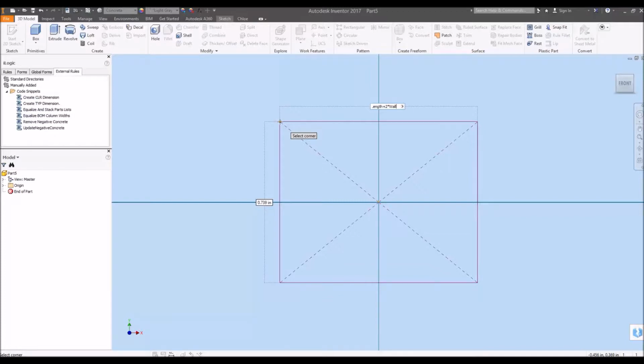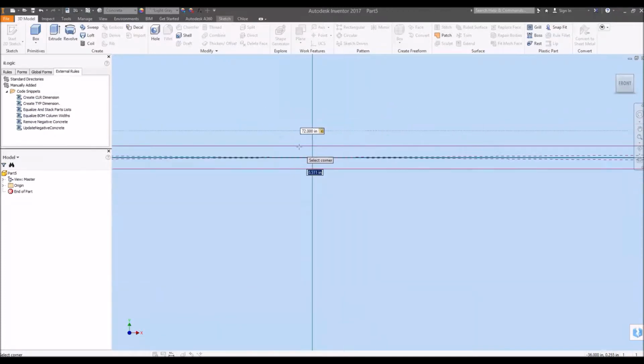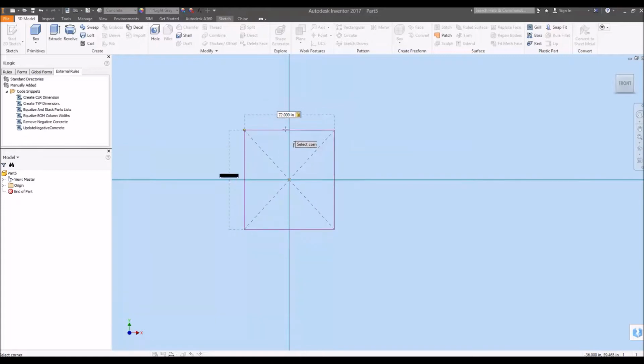Go ahead and hit the tab button to reduce the time spent clicking, and it should automatically put you into edit mode for that vertical dimension on the left there. If you see it highlighted in blue, we're going to basically do the same thing. We're going to type in width plus 2 times our wall, it changes from red to black, and let's go ahead and hit enter.